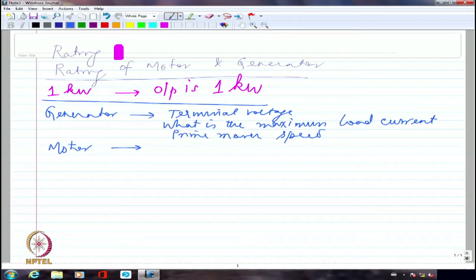So we are going to specify here the rated IF, at which the generated voltage will be at rated value, which can be slightly higher than whatever is my terminal voltage. That's why I'm getting regulation.